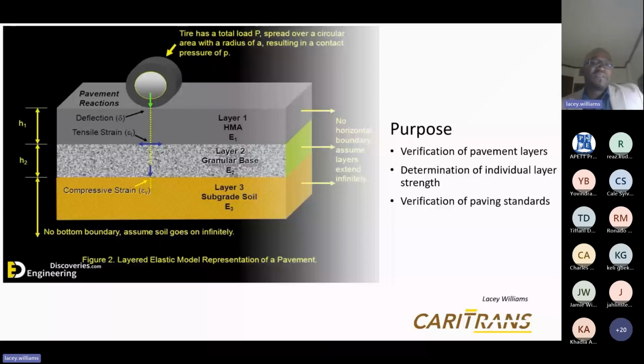seeing a 20% degradation. Well, of course, if we call the pavement deterioration curve, once you get onto that curve and you start sliding, then there's no stopping until such time as some level of intervention is made. So in addition to other pieces of equipment like a ground penetrating radar and so on, you typically use this to understand what is happening on the subsurface, right?